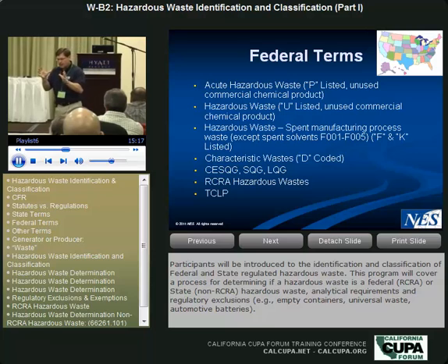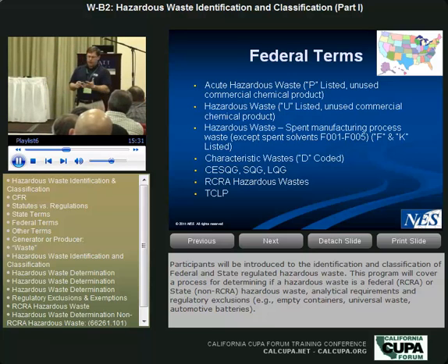And when I take my different materials that I use in a particular process and I collect the waste that's produced from the process, that waste comes from a process where those chemicals have been used and spent, and those are candidates for F codes and K coded federal RCRA waste. And then for hazardous wastes federally, we have 4 predominant characteristics.